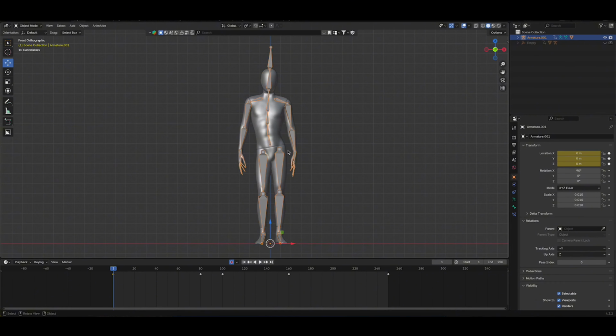The next step, I want to prepare the T-pose and the morph pose, which I'm going to dress up before I animate that. In order to do that, I just need to go to the pose mode again, select all of the bones of my avatar, select all of the keys except the very first one, and just delete them. So as you can see, now we have the static model. The next step is to select the very first animation and move it onto the 20th frame. So it's still static.